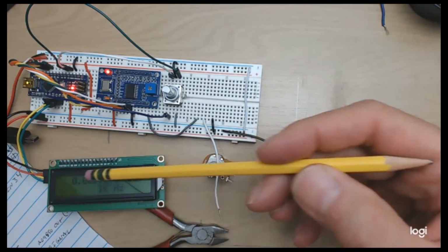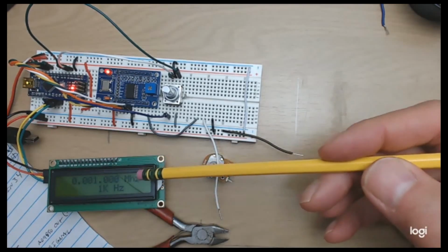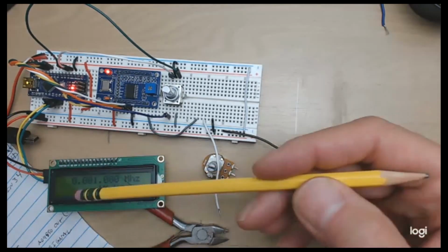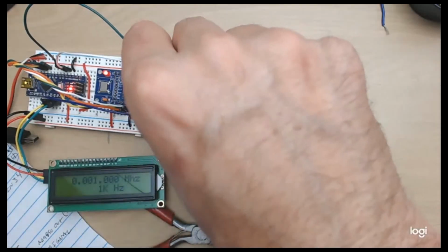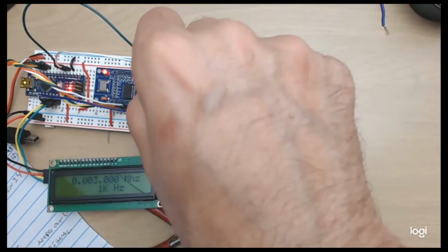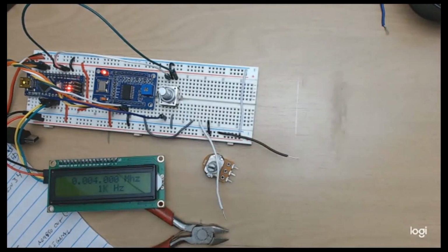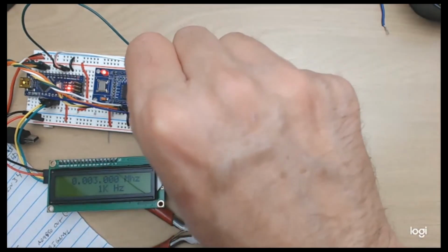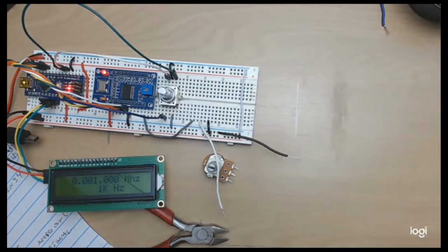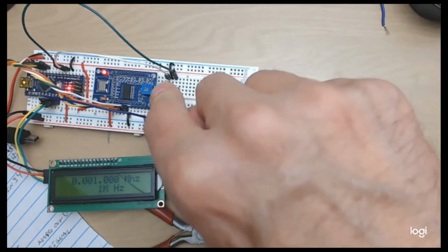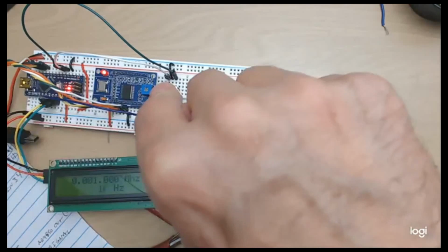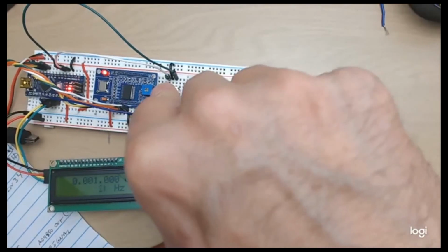All right, so it's showing that the frequency is set to 1 kilohertz, and the frequency update is set to 1 kilohertz, which means every time I turn the dial, it should go from 1 to 2 to 3 to 4. Now that's good, because that says that the encoder is working properly, that I can tell clockwise and counterclockwise. And then the button controls the frequency change increment. So when I hit the button, it's going to go from 1 kilohertz to 10 to 100 to 1 megahertz. All right, so the controls are all working.